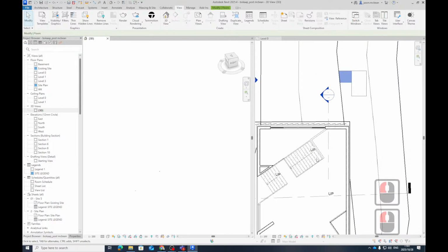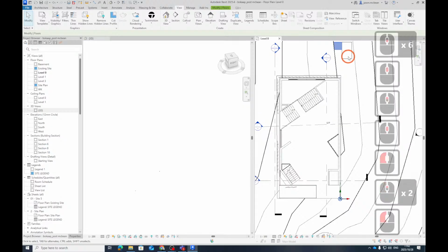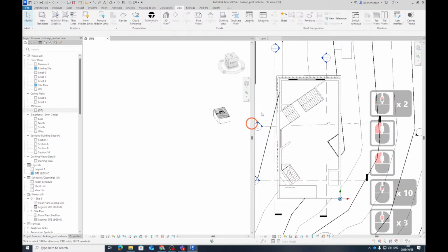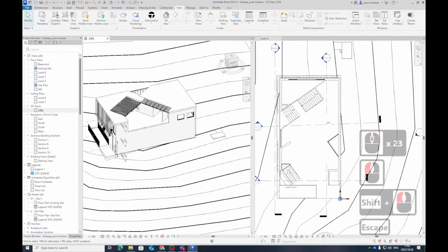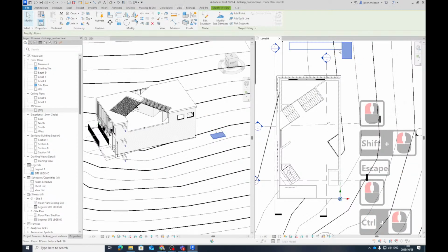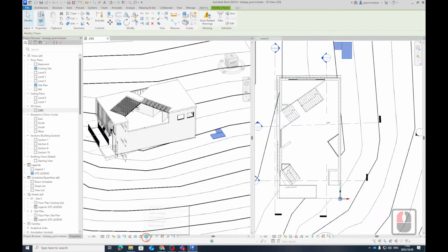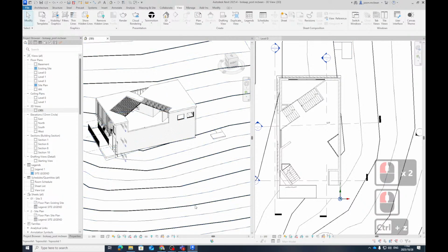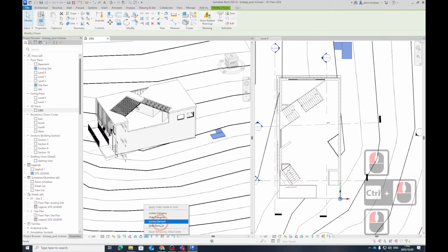So it means that while I'm working on the one, I can see what's going on over here. Okay, so if I select that object, you see I'm playing while I'm working? So if I select these two objects just like this, and they're all attached to level 0, and I say isolate element. Undo, so I've done it in the wrong direction. So I'm going to say isolate element.